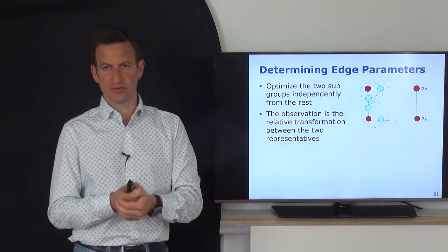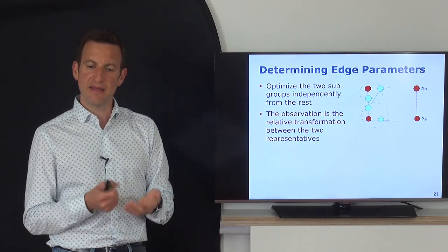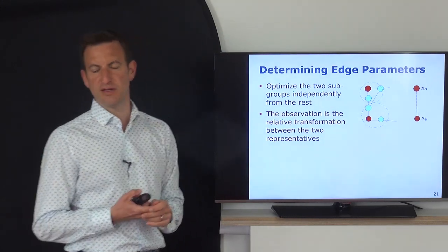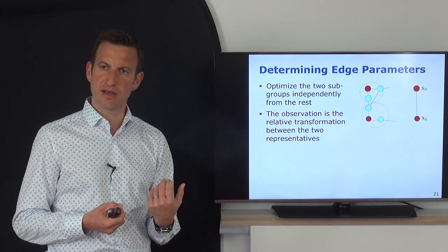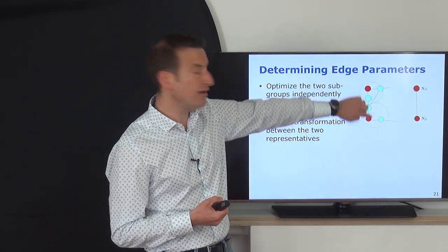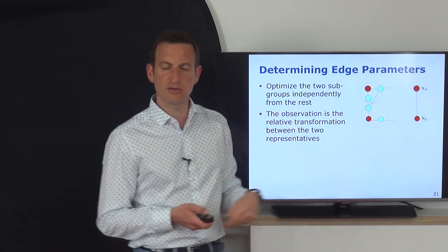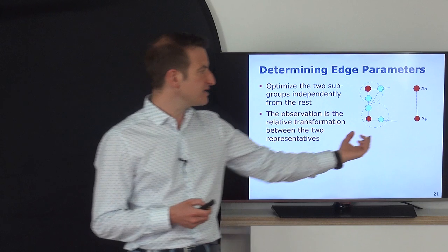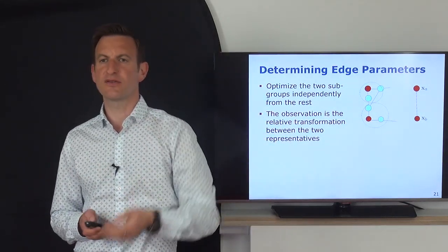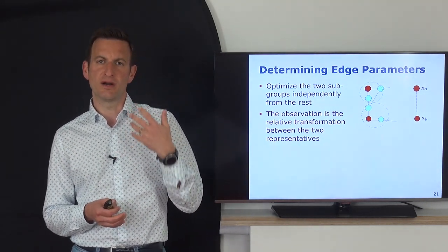In addition to this, I want to have uncertainty information. I want to have the information matrix associated to this constraint, because I need to know how much information is stored in there. And again, that's something that we can do as well, given what we have learned in the past about pose graphs, basically computing an uncertainty of a node with respect to another one. So let's say we assume this one to be fixed, so what's the uncertainty to go from A to B? So what we can do is we fix, in the small optimization problem, this node, so we take that node out, invert our H matrix, and then take out the corresponding block that represents the node XB and invert this small part. So this was the end of the previous lecture on pose graphs, the 1 or 2 slides explaining how we are computing these uncertainties.